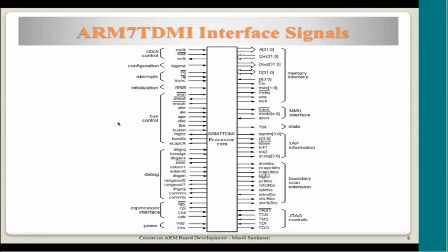So the pin numbers could be anything. It is independent of what is coming out of this core. That is dependent on the vendor who bought this ARM core and built an SoC. So when ARM is giving the description of the signals, it doesn't talk about pin numbers. Hope you understand why there are no pin numbers in this description.